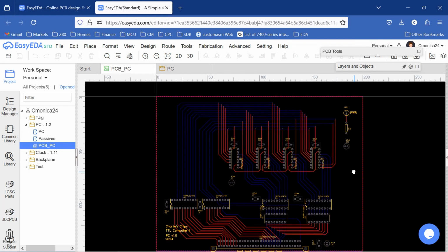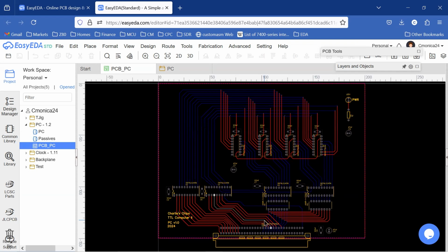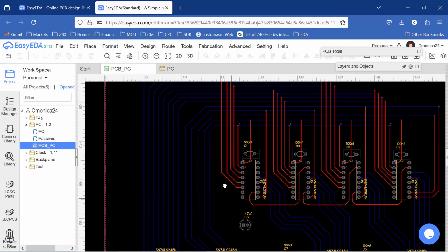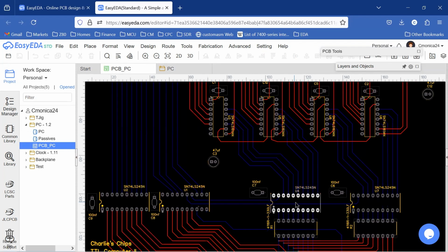So we're taking the card edge inputs coming in through these two ICs. I brought them up and around this way on our card. Here's our four LS161s, our counter ICs. Their inputs are pulled down from the bus lines above, and then our output signals are coming down from our 161s and into our output buffers.